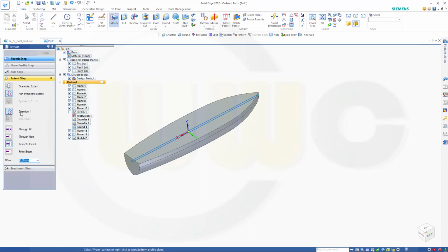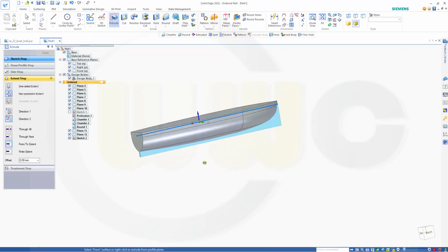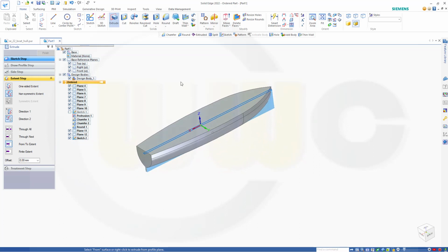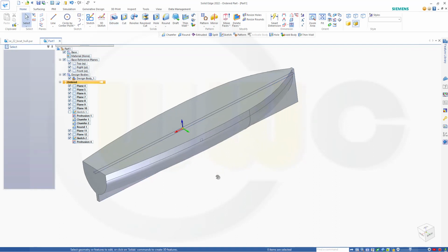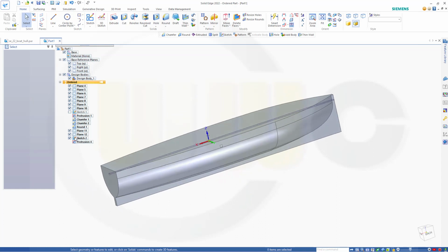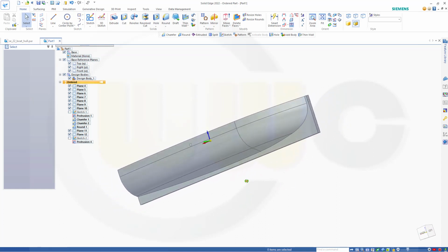Accept. It should go from to extend, so right click from the sketch plane to this one here. Yeah, great. And the second direction from the sketch plane up to this one. Finish, cancel this out. Now hide that sketch and add a round of fillet